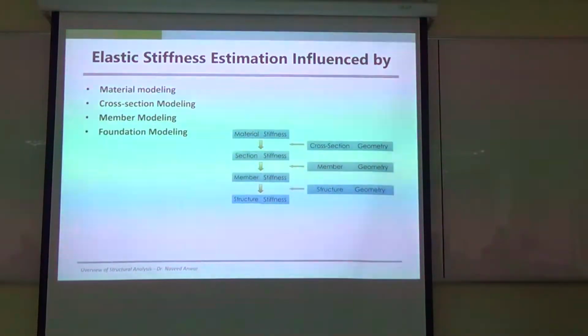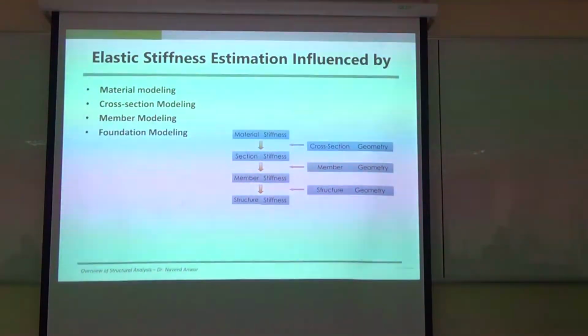And for a typical tall building, let's say a 40-story building, the difference between a gross cross-section stiffness and a cracked cross-section stiffness is about 1 second. That's a lot. A 15-20% difference in this natural period can come from the cracked or uncracked section, and we do not know the real situation. That's why many people try to run model analysis for different values of stiffness.